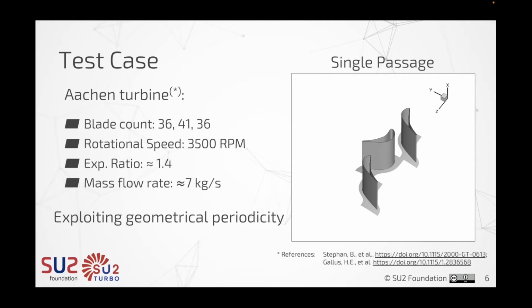Instead, if you're using another kind of interface that was not mentioned or just slightly touched during the previous session, something like the frozen rotor, pitches have to be equal, unless you have some more fancy boundary conditions for the periodics, which we won't talk about during this session, and I think are not even available in SU2.